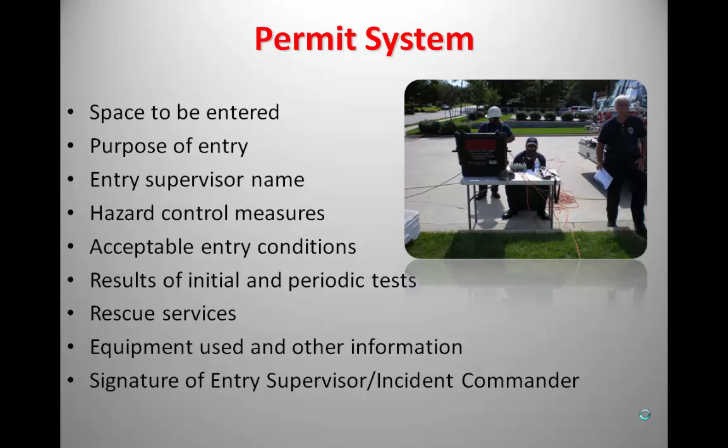So here you see this list of several aspects needed for a permit. The permit attributes are defined in the OSHA standards, so these things you see here on any confined space permit have to be addressed. And here's some of the verbiage I was mentioning earlier about the OSHA terminology. Entry supervisor is an OSHA term for the person that is in charge of that entry. In our world, incident commander would be that.